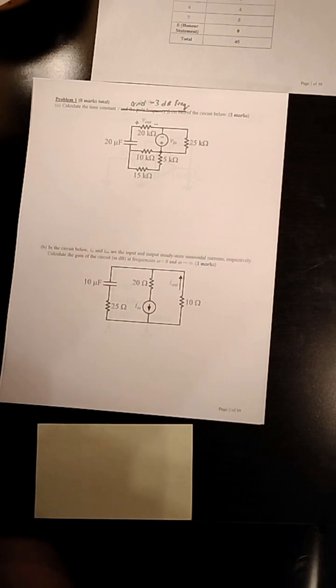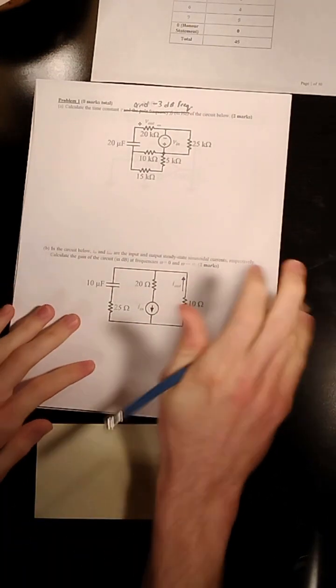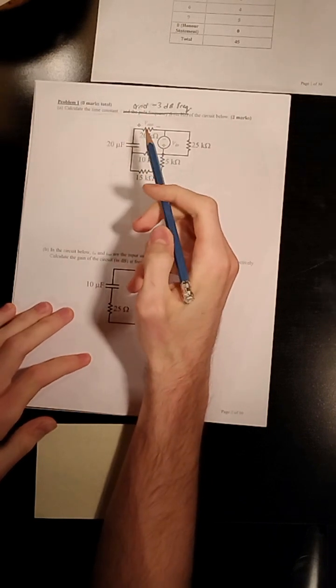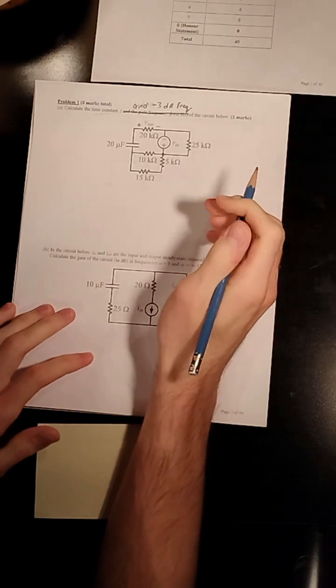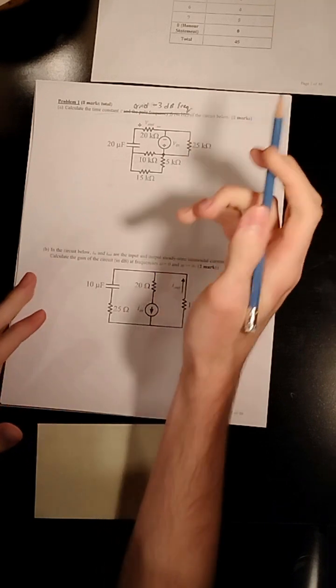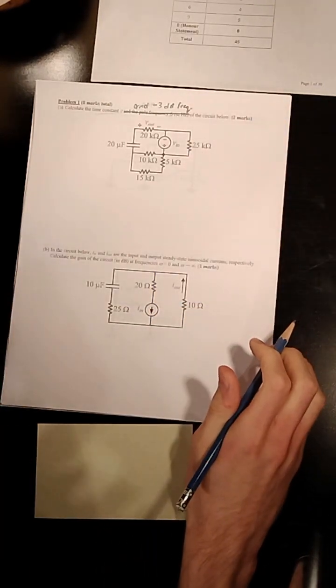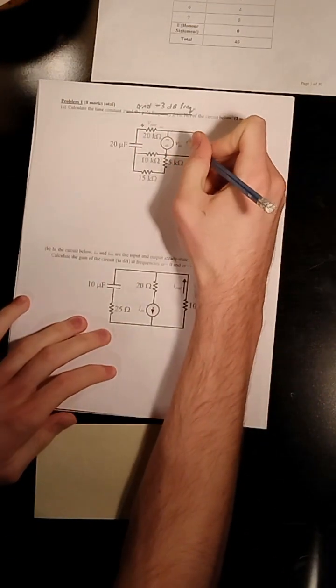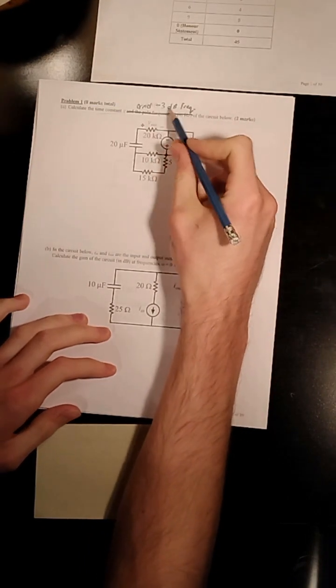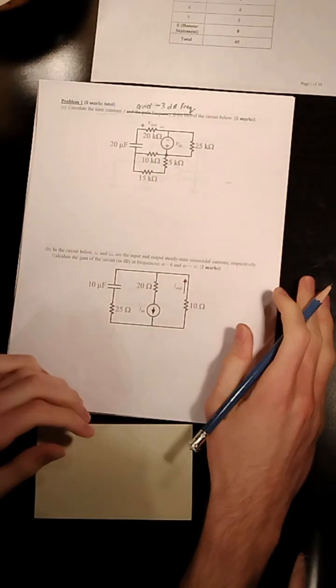So I'll give you 5 seconds to ponder the problem. 5, 4, 3, 2, 1. Okay. So this problem initially confused me a little bit because the time constant has to do with the charging of a capacitor from a DC voltage, like an RC circuit, whereas the decibel frequency has to do with AC, sinusoids. What I believe is going on here is that V in, you should treat as DC to find the time constant, and then you should treat it as AC to find the -3 decibel frequency. So that's what I'm going to go with.